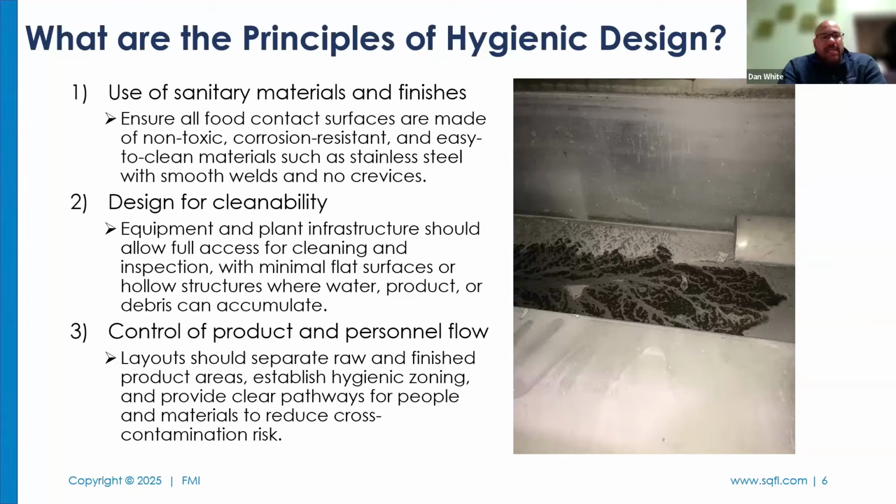I see this a lot of times, that companies sell a lot of CIP capable pumps. And I would argue that companies put a lot of faith in the fact that that is a wash down pump. But I don't have enough fingers or toes to tell you how many times I've torn apart a positive displacement pump and found product packed in there that could carry allergens or contaminants, things like that. So you need to make sure that it's designed for cleanability.